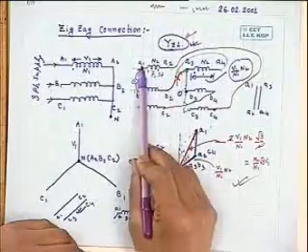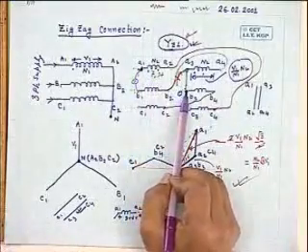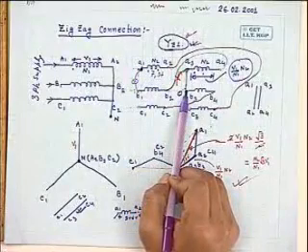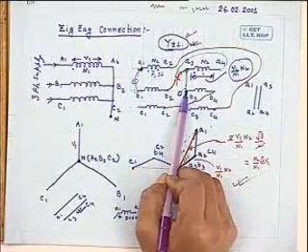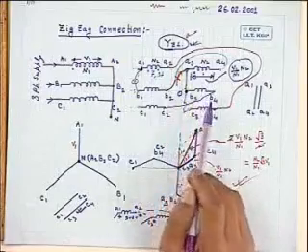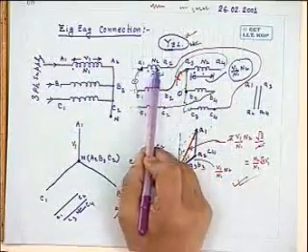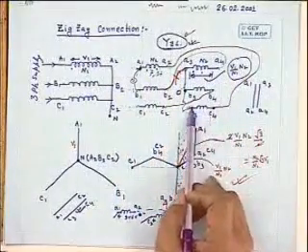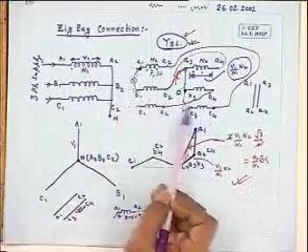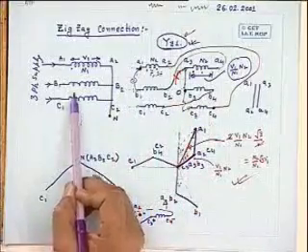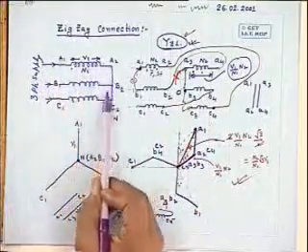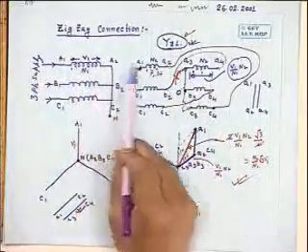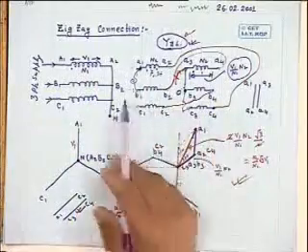So if you connect a single phase load between one line and the common point of the secondary of a zigzag connected transformer, what I am trying to tell is that single phase loading is possible, no problem, no neutral shift will occur. Why? Because this A phase will carry current on the secondary side, C phase will carry current, and both of them will have their own reflected currents on the primary A and C, and it will complete its path.